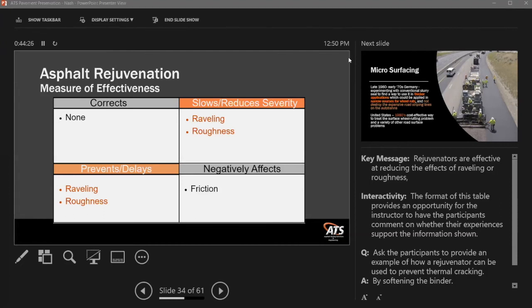All right, thanks. For the sake of time, I will try to get through the next sets a little bit quicker. Again, with asphalt rejuvenation you're looking primarily at trying to keep that top layer young, but be careful because it is a top layer emulsion. Watch your friction values and make sure it's going to wear off that top portion just to get the rock friction back.